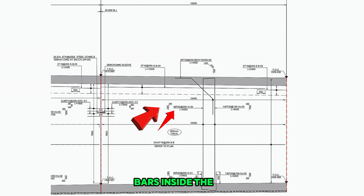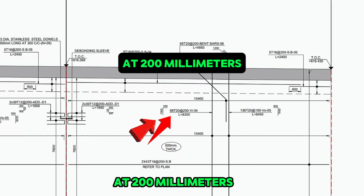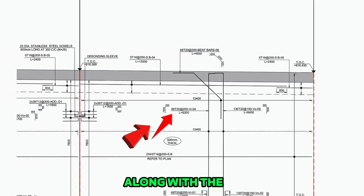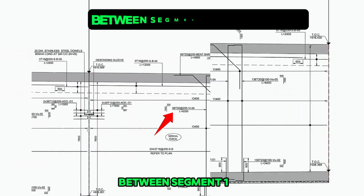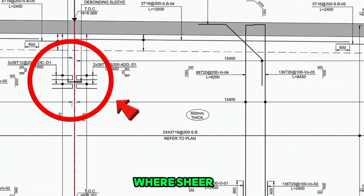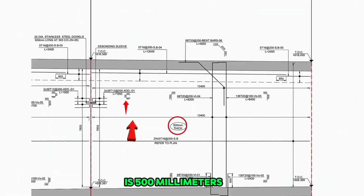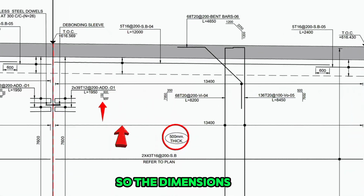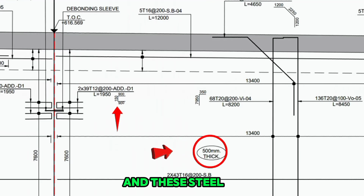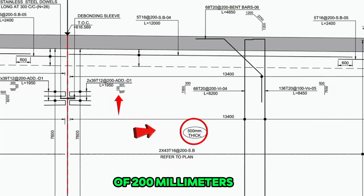The vertical steel bars inside the wall have a spacing of 20 millimeters at 200 millimeters, and their reinforcement details have also been provided, along with the dimensions of the steel. Between segment 1 and segment 2, there is a construction joint where shear connectors and additional U-bars have been used. The wall thickness is 500 millimeters, so the dimensions of the additional U-bars are 150 millimeters, and these steel bars of 12 millimeters will be used from bottom to top with a spacing of 200 millimeters.